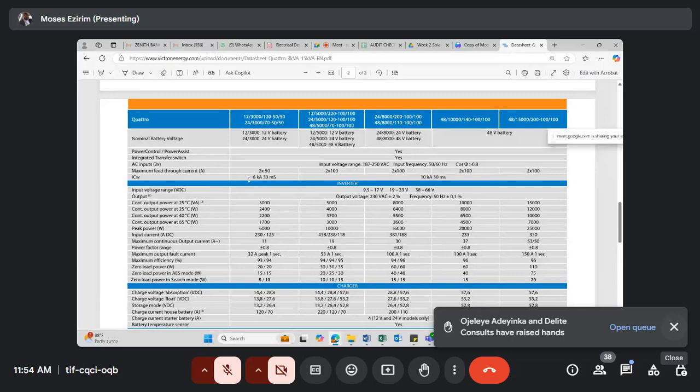Is the battery not going to get low? At the end of the day, the customer will be complaining, I didn't use this thing within 2-3 hours, the system went off. So I want to be very clear. During the peak sun hours, if the inverter is taking from the battery, is it not reducing the capacity for night use?